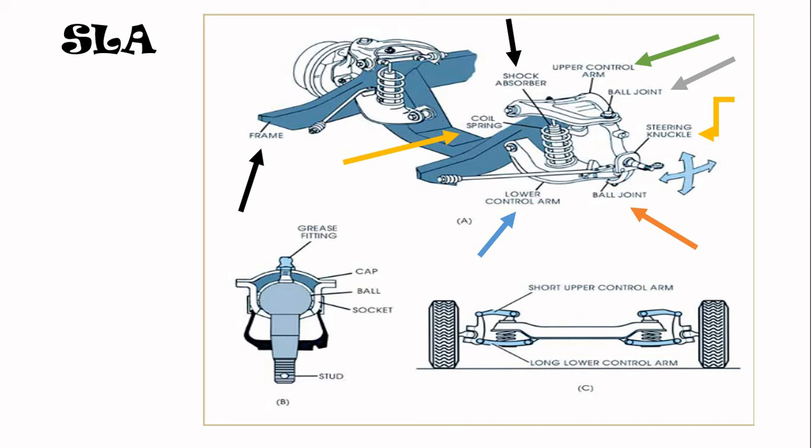At the same time, each front wheel can be turned left or right to provide steering control. The ball joints permit the combination of movements: the flexing of the assembly to absorb road shock, and the pivoting of the steering knuckle, spindle and wheel to let the driver steer the car. Because the pivot points and other points of motion can vary as they move, these parts are usually equipped with grease fittings for regular lubrication.